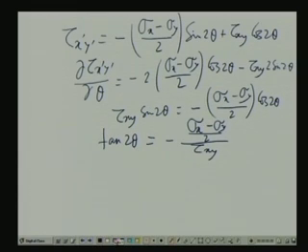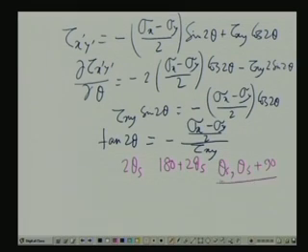Now, here also, as we have noticed earlier, there will be two values of theta defining the two perpendicular planes on which the shear stresses will be maximum, those angles being twice theta s and 180 degrees plus twice theta s. So, in the stressed body, theta s and theta s plus 90 are the two perpendicular planes on which the shear stress will be maximum.